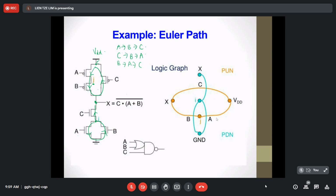When you draw the stick diagram, you can use any one of these ULI paths. If you use a different order of the ULI path, that also means that your connections will be different. So for any question like this with more than one ULI path, as long as the ULI path that you get is in only one direction through each of the transistors, it will be considered correct.